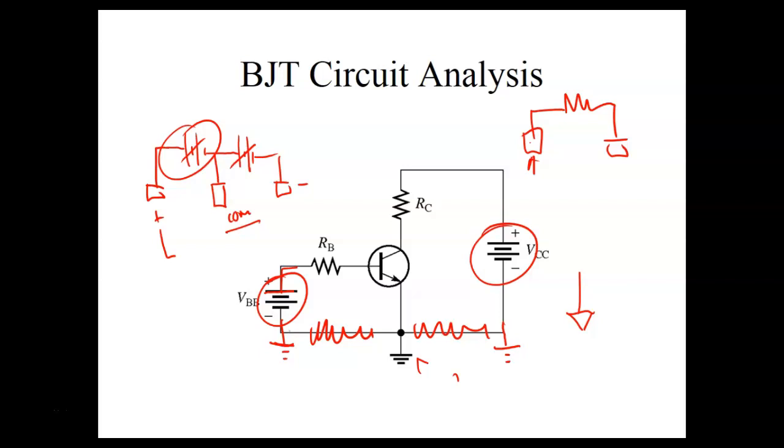I've seen this several times where you've got the output of your power supply, and you're supposed to put a capacitor in parallel with the resistor. And I've seen this more than once, guys, where you put your capacitor over here, and then you put your resistor over there. This is not in parallel, this is in series with that resistor. I've seen this twice already in labs in this class. Parallel means the two leads connect together, right? You understand that?